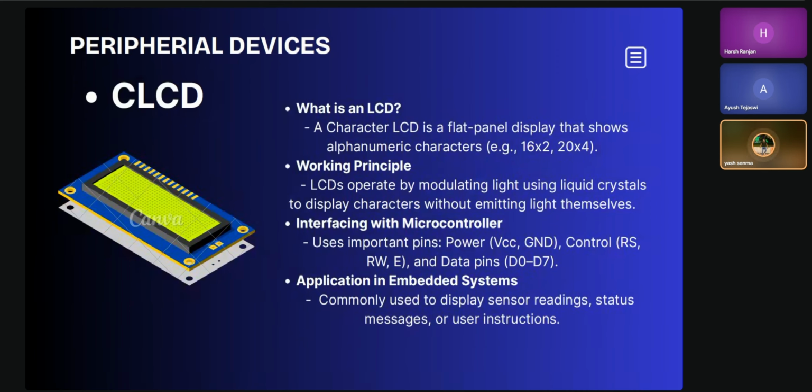The 16x2 LCD was our primary user interface. It displays the startup message, select mode, for example quick wash or deep clean, the current cycle, and a completion notice. Interfacing was done using data lines connected to the microcontroller port pins, and control lines for read write control.